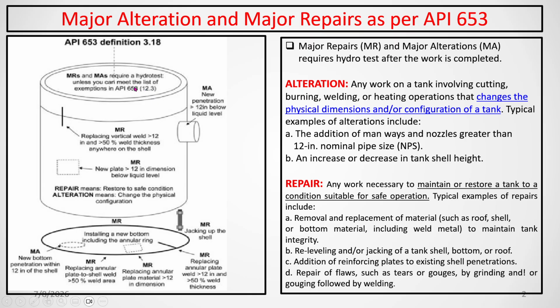They require a hydro test. After this, we are required to do the hydro test, unless you meet the list of exemptions given in API 653 12.3. They are giving some exemptions. If the exemption is applicable, then you need not do the hydro test. Otherwise, after every major repair or alteration, you have to do the hydro test.